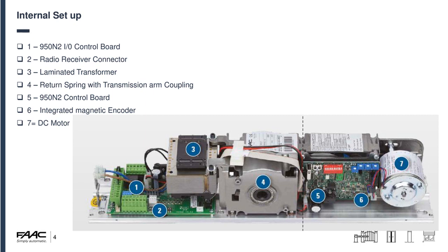Like I mentioned before, you can add in receiver cards for wireless pads, also our XT868 handheld transmitters. You can integrate those regarding different forms of access control. Also, obviously, along with keypads, fob reads, etc., if they are wireless. And also, you can plug in an interface card if the wireless activation is going to be on a double door set.